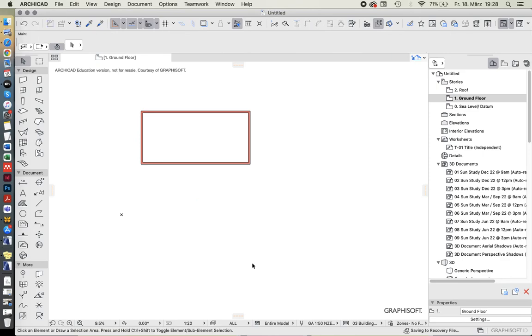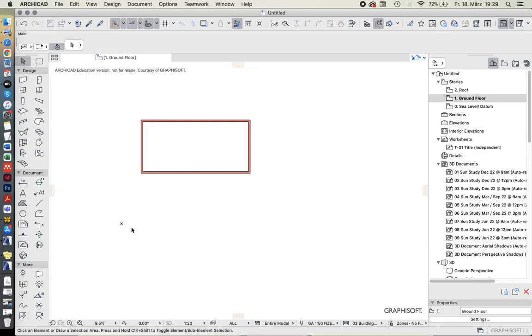We'll just delete that for now, as it's a bit annoying as well. And lastly, you can see there's a tiny X here on the bottom. That one is the origin point of the document. So there's an invisible grid behind, and that one is 0, 0 within your axis system. Make sure that your main drawing is somewhere close by to that origin point.